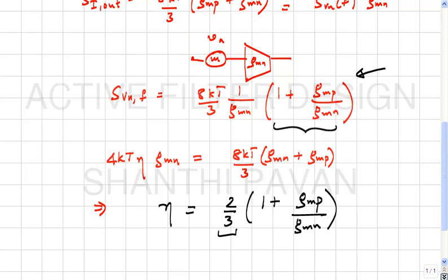So if you take these two as a pair, then the equivalent signal to noise ratio of the pair is degraded when compared to just that of the NMOS transistor. That's all, right? I agree completely that the PMOS transistor is, as far as signal is concerned, completely redundant. But in the real circuit it is definitely needed, because the PMOS transistor pushes down that current.